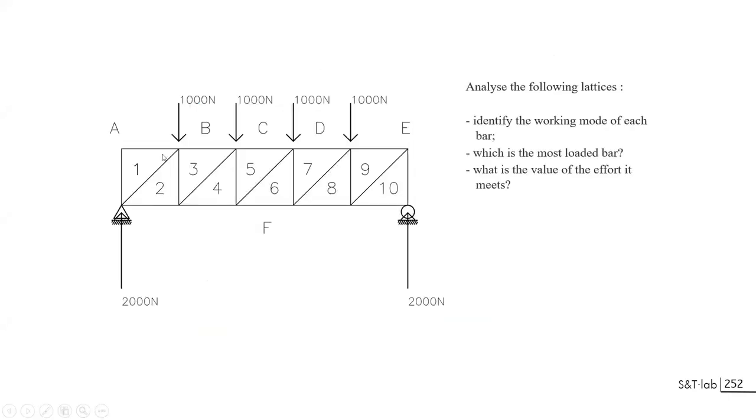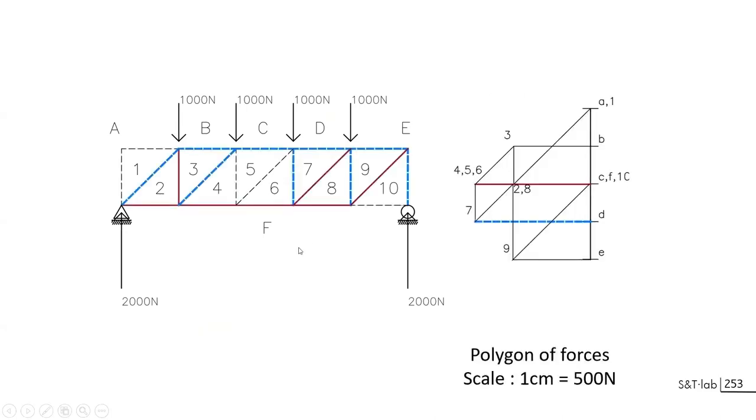an unsymmetric system in which we have bar, you can know that this is compression and this is tension, but what about the system in the middle? Going to the solving of this truss, we show you where the bars are changing direction. So diagonal will be equal 0 here, and diagonal with change of sign becoming tension. Hence, it was compression in the very beginning.